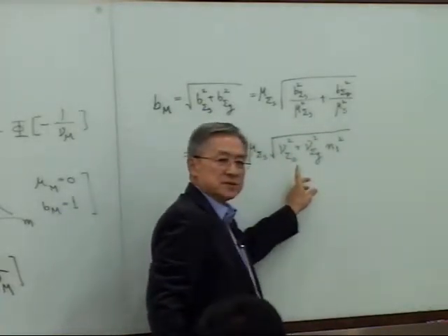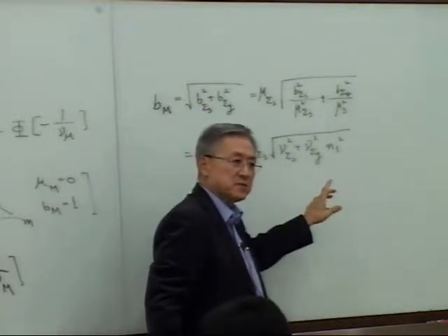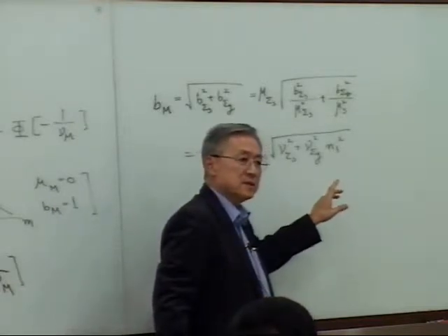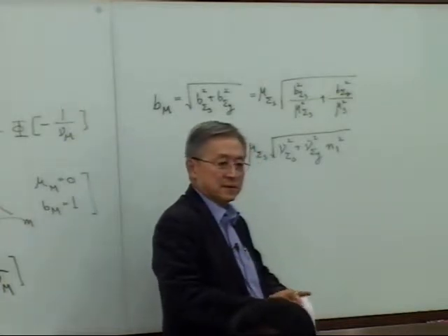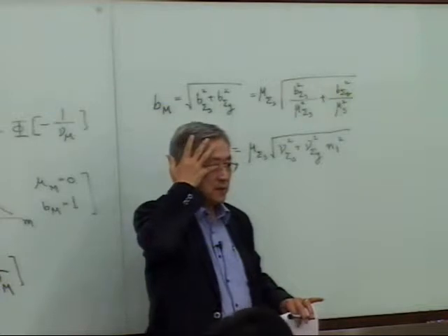What's a mu here? Mu sigma S square. What's a mu here? Coefficient of variation of sigma S. And what about the N1 there? That's a central safety factor.